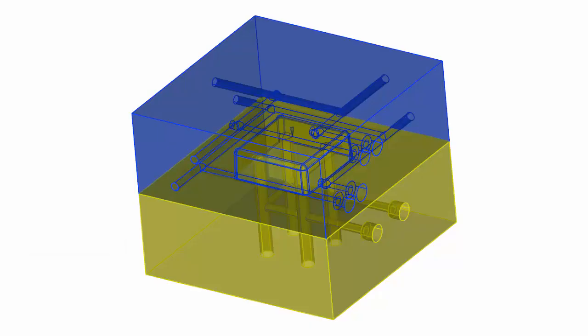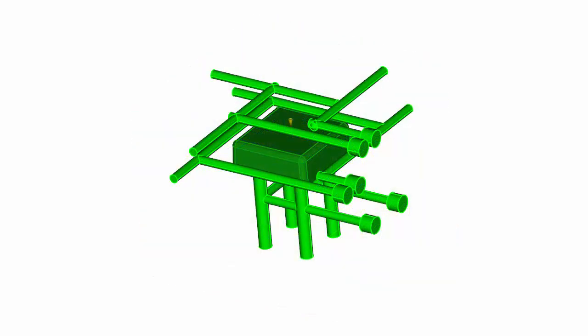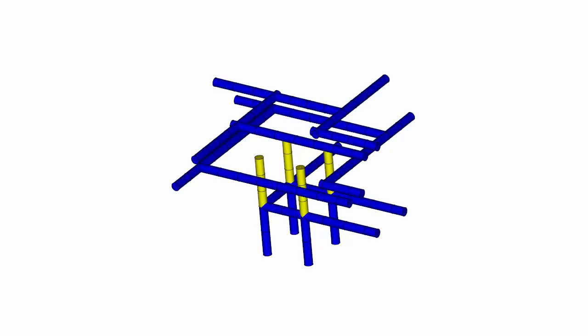Cooling channels are frequently designed in a CAD package and imported into Autodesk Moldflow Insight as 3D bodies. These 3D bodies need to be converted into beam elements for most cool analyses using the center lines of the 3D bodies. Extracting center lines from even a simple cooling system can be a lengthy process. This video shows how to convert suitable 3D bodies into beams.